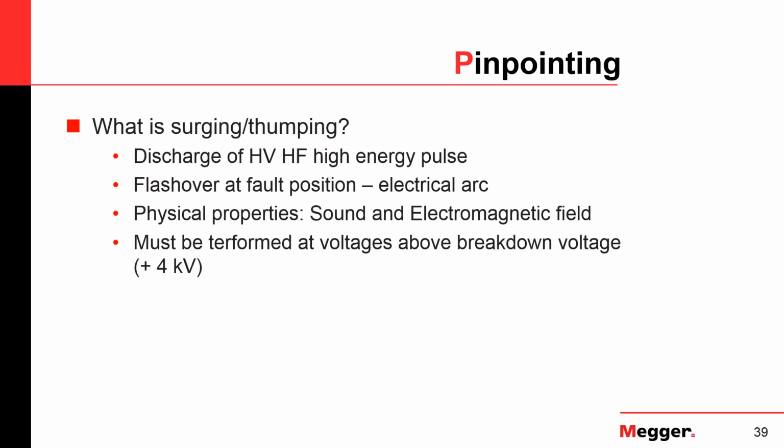In this case, it is not filtered as before. While the arc reflection, the prelocation, is filtered, the thumping is done at an unrestricted energy level, so to speak. And if you would demonstrate this in air, you have a short cable, and you do an arc reflection to demonstrate this to an audience, and then you do a thump, while the arc reflection is only a kind of weak sizzling, the thump is actually like a gunshot. So it's really loud, and it's actually really powerful.